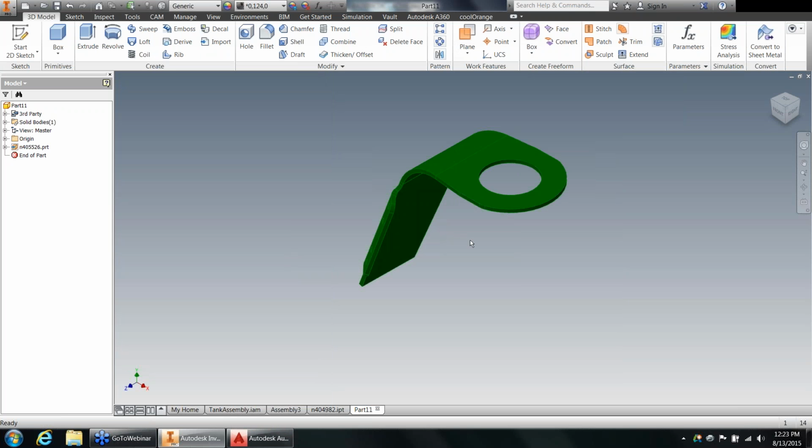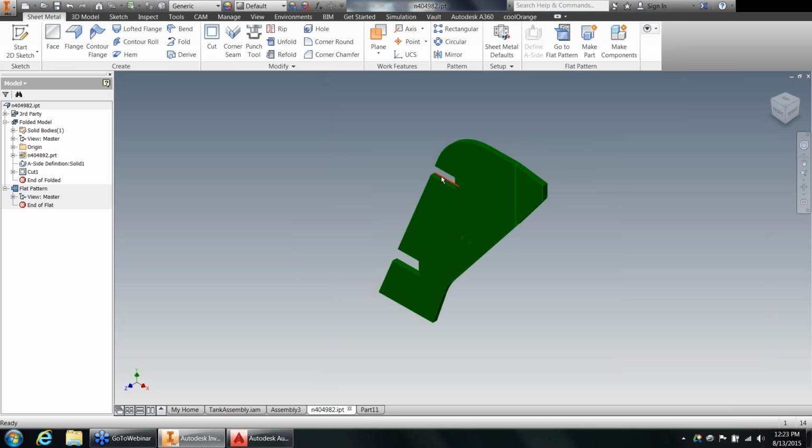So some other questions that have come up a couple of times is, if you modify these components, in this case, I went in and added a couple of rectangular cuts to this model, is that going to show up in the native formatted file? No. Right? These are features that have taken place in Inventor after the importation of that document. They don't translate back to their neutral format, so they don't go back to Catia or SolidWorks or Pro-E.